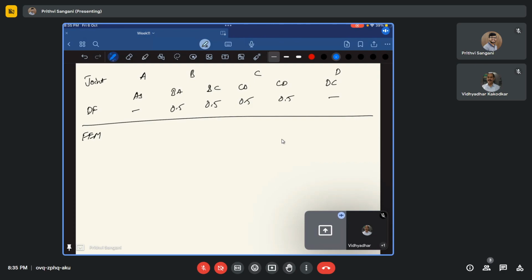When the material is in the elastic range, superposition is valid. What does superposition mean? It means that you can rotate and then displace it, find both the moments M1 and M2, and the final moments will be M1 plus M2. Okay, that is what it means.